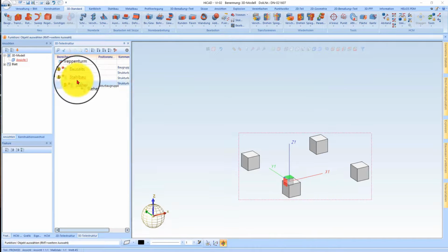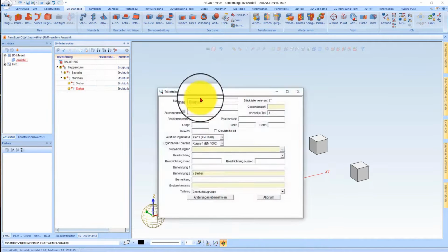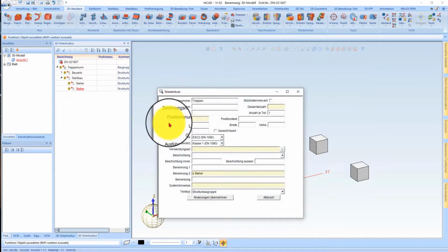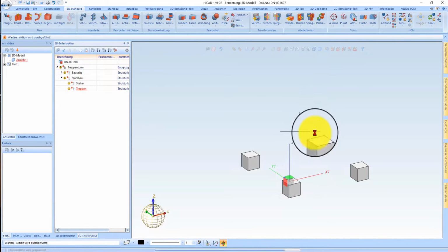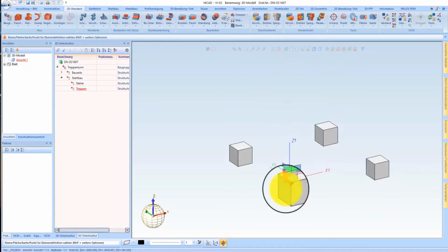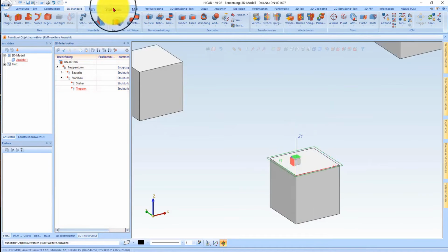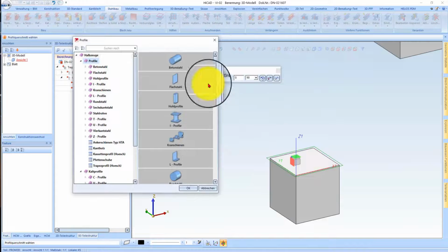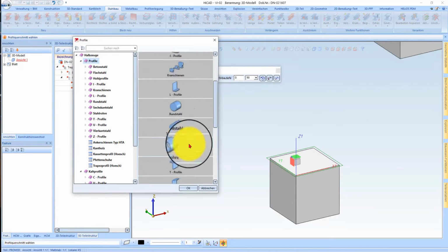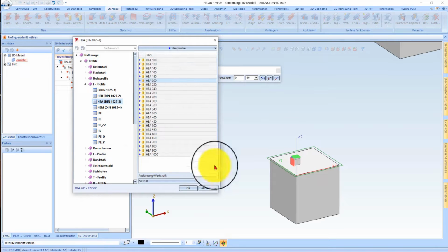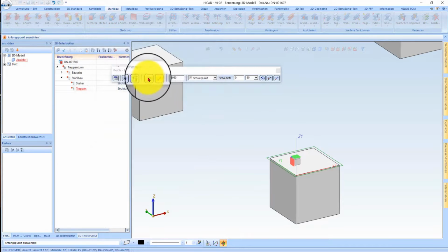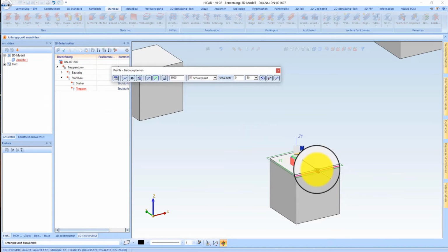So I will also definitely need stairs right away. So everything I know right now, if I have posts and I have stairs, I know this from the ground up. So I will now place this onto my editing layer, and I want to immediately install a beam, which I will select from my library. So eProfiles, I will just take the HRA 200. Of course, I can change this at any time, where I then create it vertically on the editing plane with a certain length. So that means I will simply place this one here,